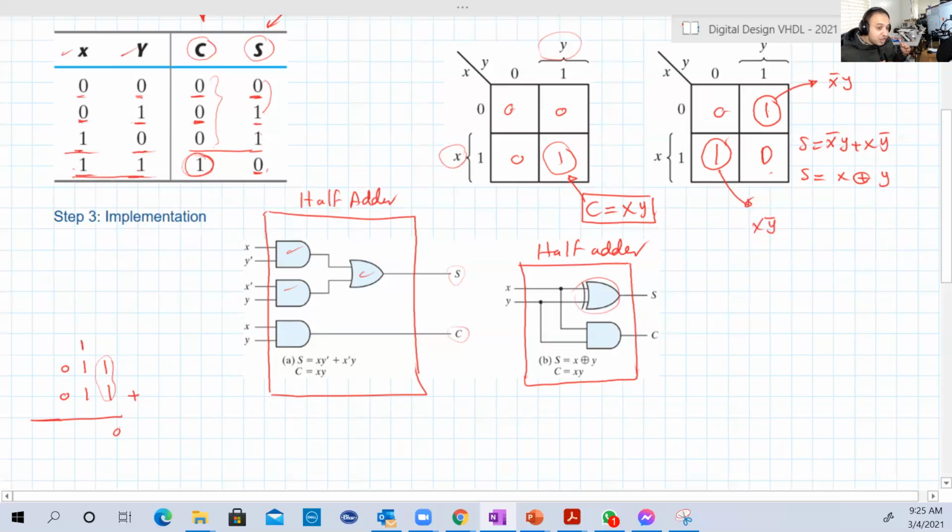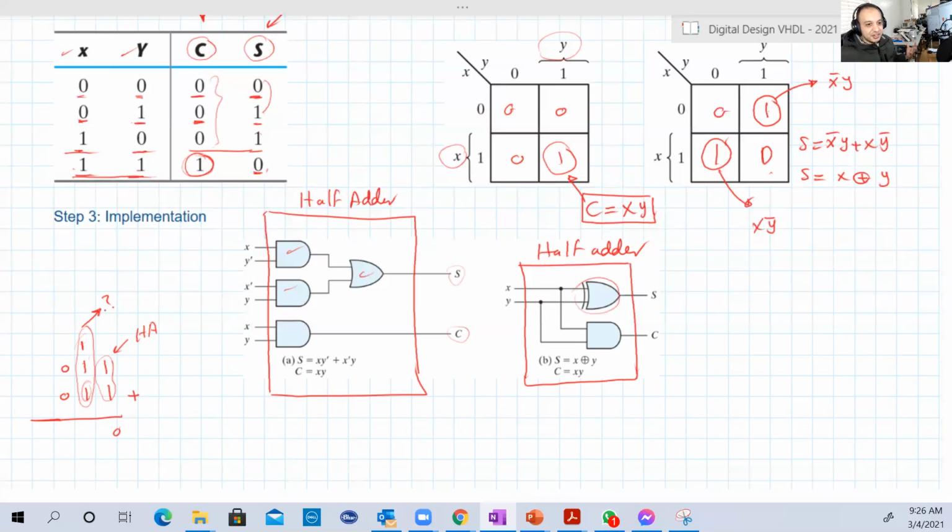And now, before we continue, let's look at this. So here you will add 3 bits together. So you're gonna add the carry to this guy, then the result will be carried or added to this guy. It's the last one here. So this can be easily done using a half adder. But there is still a question here. Because this is 3-bit addition. Half adder is 2-bit addition.